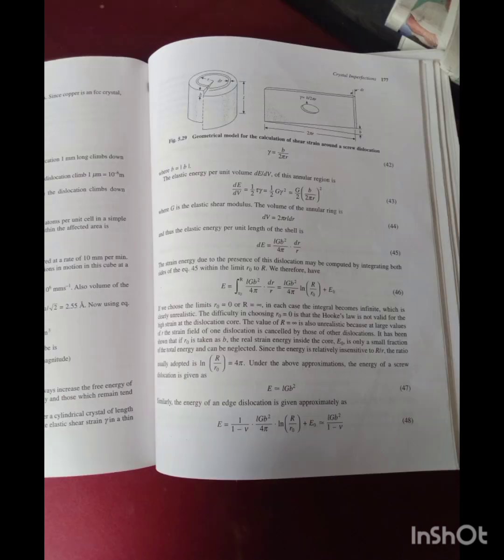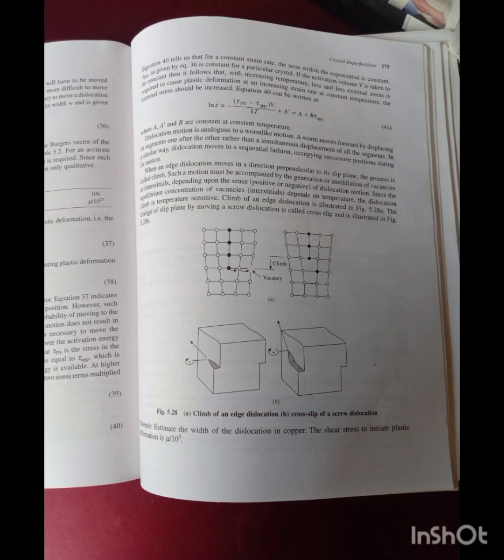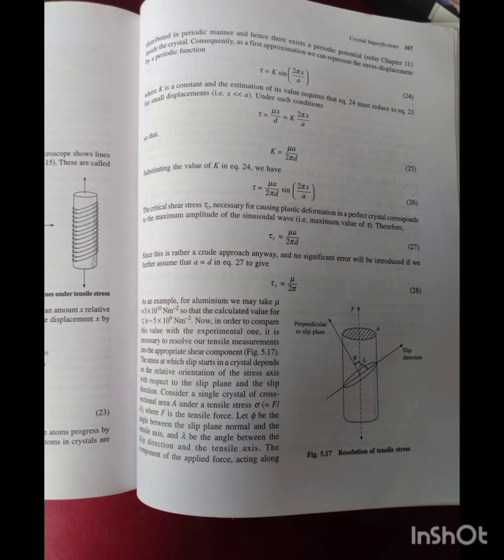The slip planes within which slip occurs are usually the most densely packed planes, which are also most widely separated. The combination of a slip direction and the plane containing it is defined as a slip system. For example, the combination of 1 1 1 and 1 bar 1 0 forms a slip system, but not 1 1 1 and 1 1 0, as the direction 1 1 0 does not lie on the 1 1 1 plane. The observed slip systems in some FCC, BCC and HCP metals and FCC ionic crystals are listed.